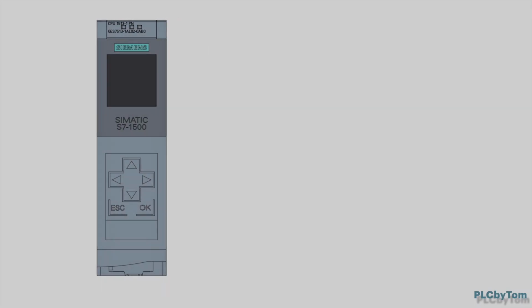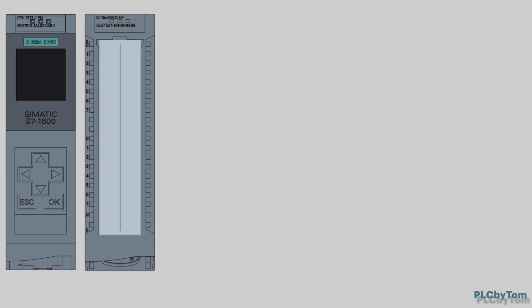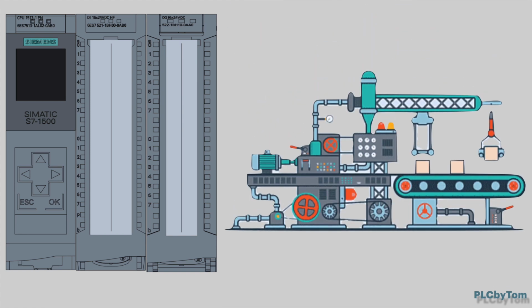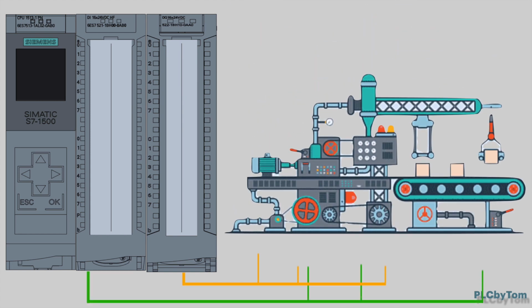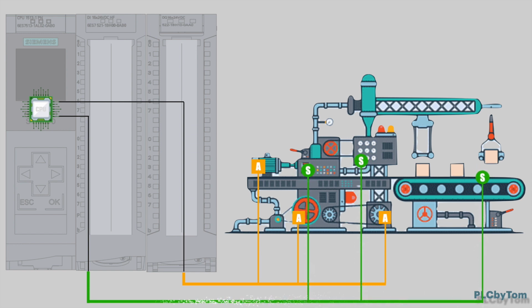As we explained before, PLC is an industrial computer which executes user programs. CPU is connected with real-world sensors and actuators via input-output modules, or shorter, I/O modules. The main task of I/O modules is to translate signals received from a sensor into low-voltage DC signals that the CPU can use. In the opposite direction it is similar. The CPU sends a signal to the actuator via digital I/O.